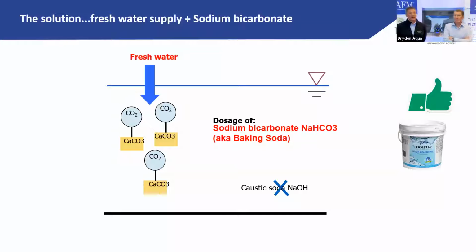This is really good, because if you don't have alkalinity, your pH will be very unstable, your water will be very corrosive, and your free chlorine measurements usually play crazy, depending on what sensors you have. Most of the sensors, if you're at alkalinity below 50, give completely wrong readings. So alkalinity is something important.